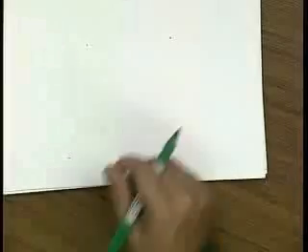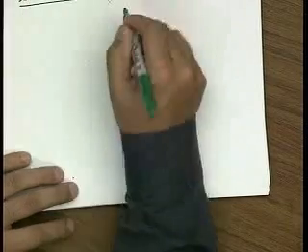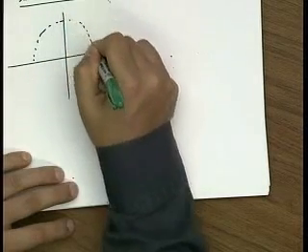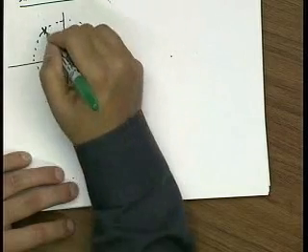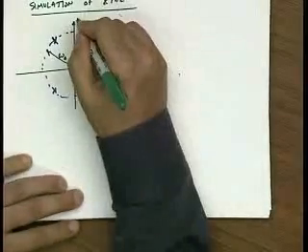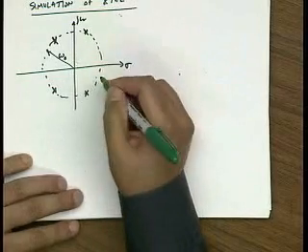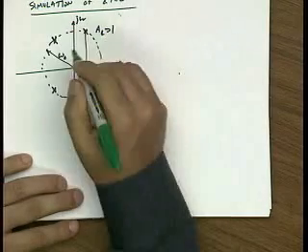All right, so one of the issues with crystal oscillators is simulation. It's not easy to simulate a crystal oscillator. And the reason for that is if we go back and look at our second order system, we found that we had poles on this circle with radius omega naught. It's j omega, this is sigma. And as we applied our loop gain, we end up with poles in the right half plane.